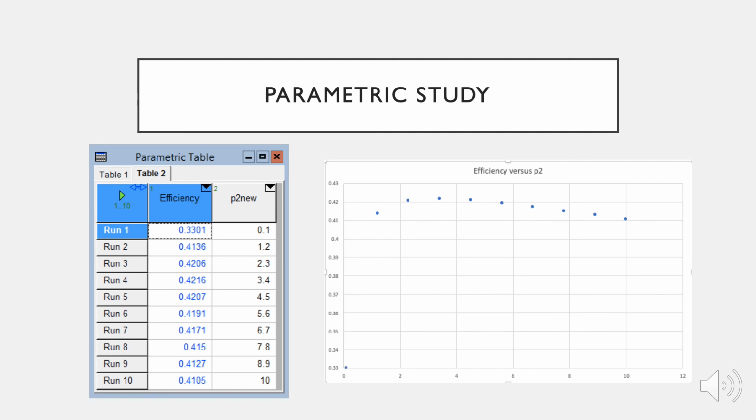So even though the new turbines only had a 7% better isentropic efficiency, using the new turbines yielded a better overall thermal efficiency of about 1 to 2%. And 1 to 2% efficiency better would account for between $10 to $20 million. So it was in our best interest to use the better turbines as opposed to the refurbished ones. Thus, we ended up with a total cost benefit of $13.5 million.